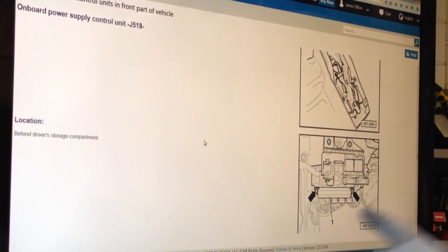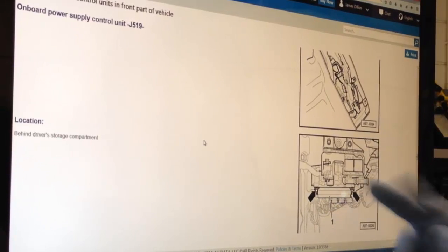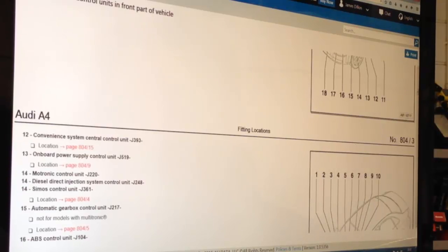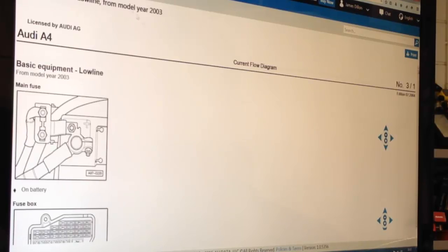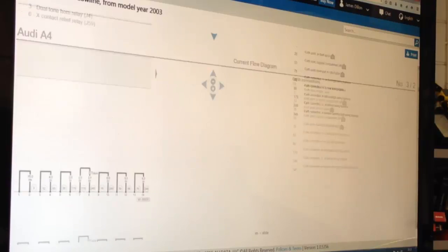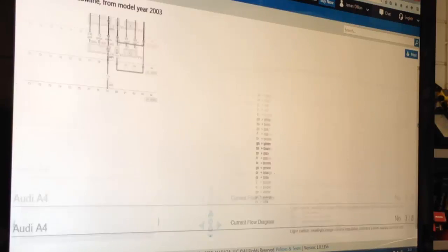If we take the panel off, what we're looking for then is this control unit, and it's showing us there, number 1, the control unit lives there. So we know where it is now. Let's have a look and see what the connectors are going to be like. The wiring diagram, if we can find that page that we were on, will give us an indication of the type of connector that we're looking for. So we need to just scroll back through the wiring diagram to find those.